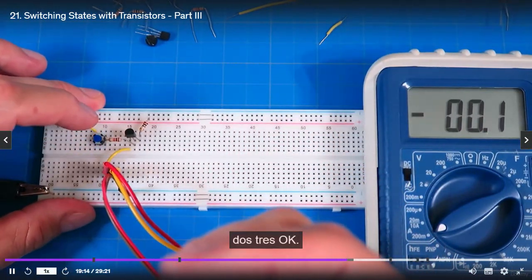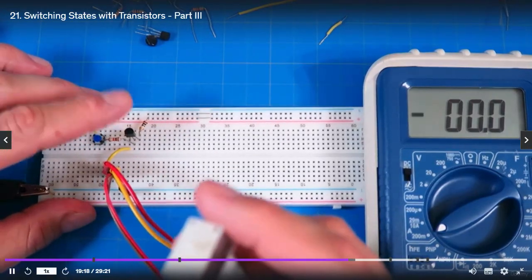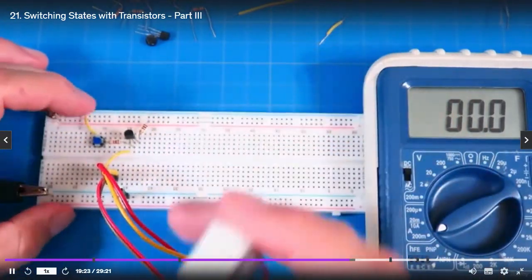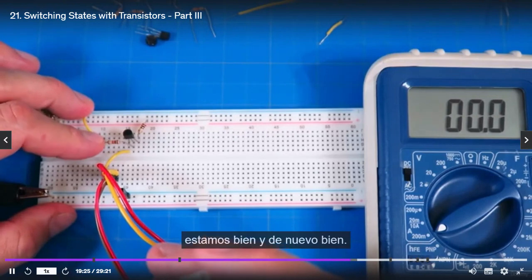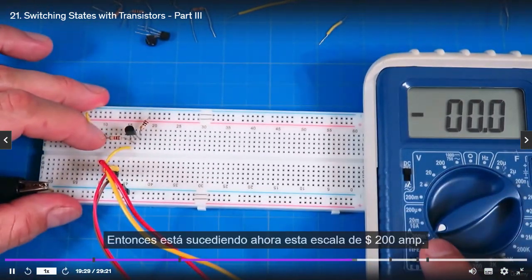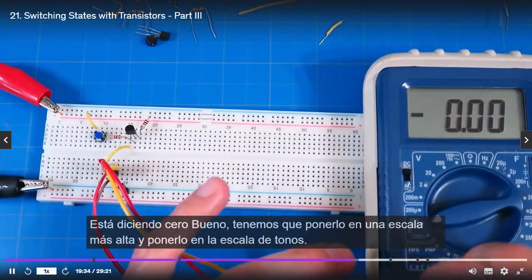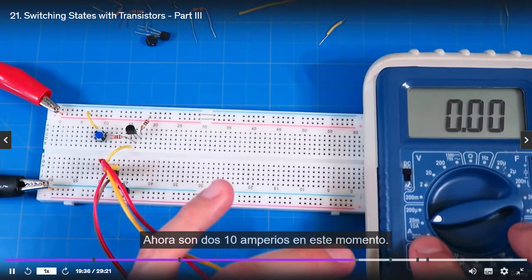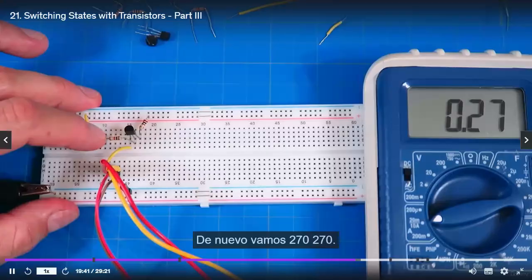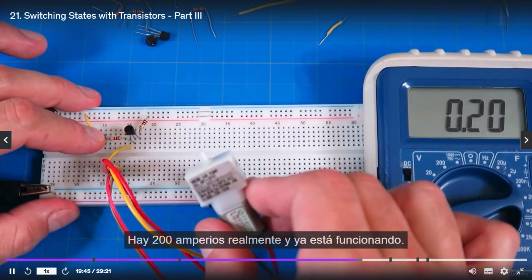Okay. All right, now I think, no, we're okay. And again, okay, so what's happening now? This 200 milliamp scale, it's saying 0L. We need to put it on a higher scale, the 10 amp scale. Now it's on 10 amp. All right, now, again, there it goes. 200 milliamps and it's going.